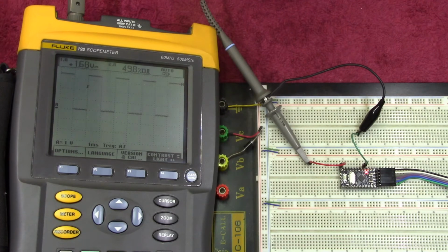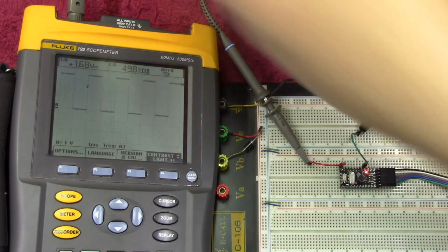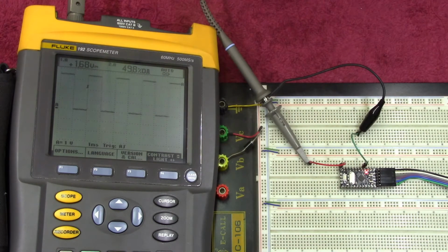So let's cut you in on the screen so you can see the programming of the Arduino. It's actually very simple to generate these waveforms out of an Arduino. It's actually going to blow your mind. But for an example, in this case it's 2.55 per percent. So if we ran it at 2.55, we expect to see a 1% duty cycle. And let's see what happens. We'll upload that now to the Arduino, and it'll reset again, and we should see our 1% duty cycle.